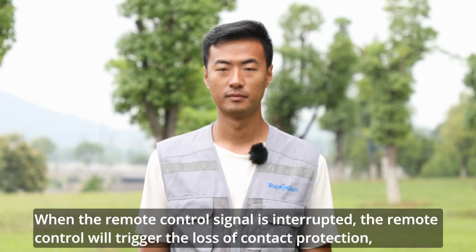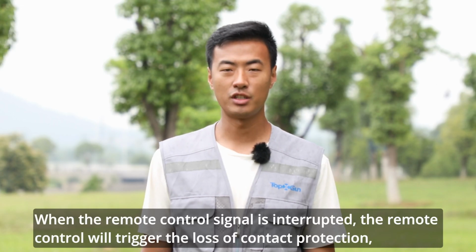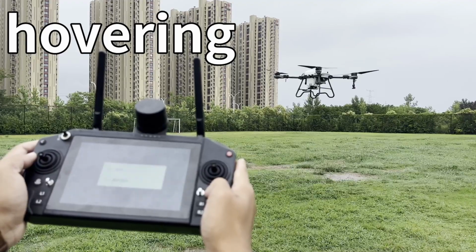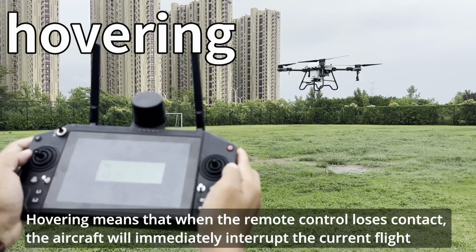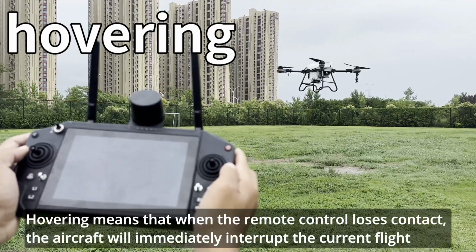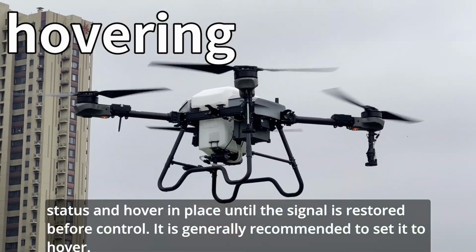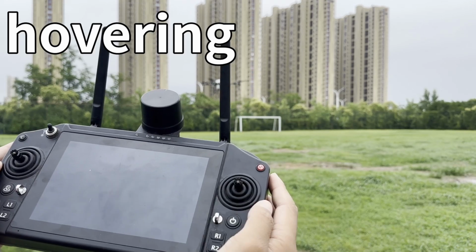When the remote control signal is interrupted, the remote control will trigger the loss of contact protection, usually with 4 protection actions: hovering, returning, intelligent, and landing. Hovering means that when the remote control loses contact, the aircraft will immediately interrupt the current flight status and hover in place until the signal is restored before control. It is generally recommended to set it to hover.